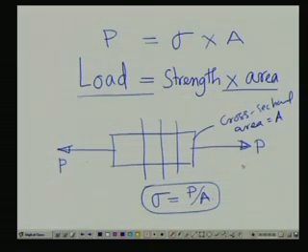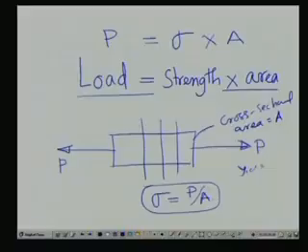Where will it fail? You can consider the failure to be yield failure. At the yield strength of the material it fails. What I mean by yield failure is that once the machine member comes into the yielding zone, it goes to a permanent deformation, or a plastic state. That also we can consider a failure, because it will not come back to its original position. So, the yield point is also a failure, and the ultimate point is also another failure we consider.